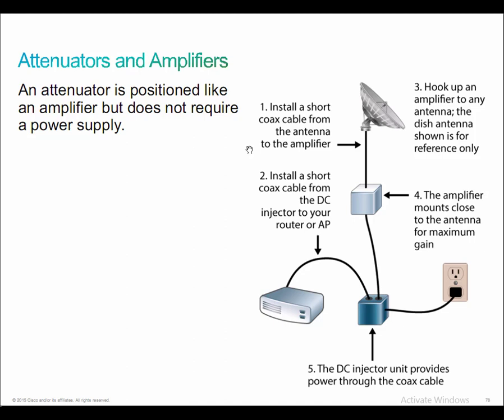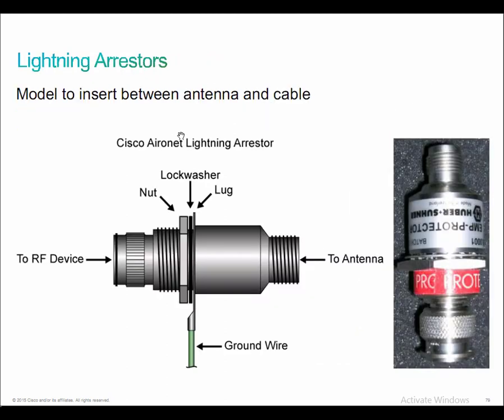If you're dealing with outdoor wireless, oftentimes you'll want to install something called a lightning arrestor. I want to be very clear about this because I've run into a situation with a client where this occurred. We had a lightning arrestor installed, which gets installed between the antenna and the cable and subsequently gets grounded to a ground.